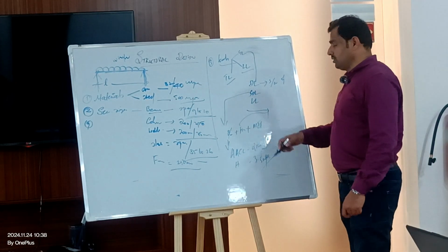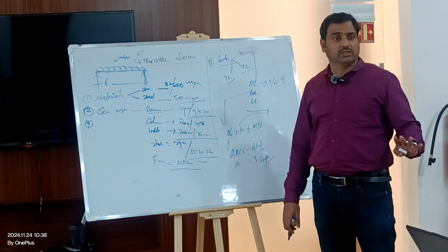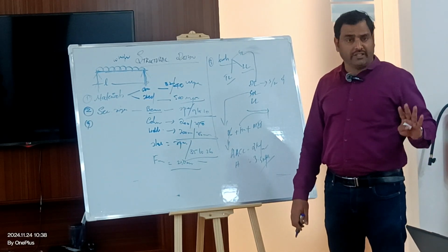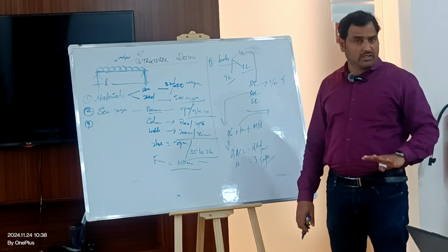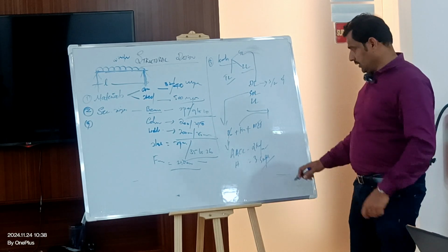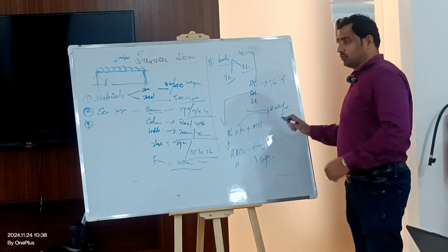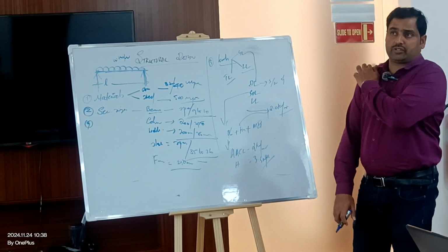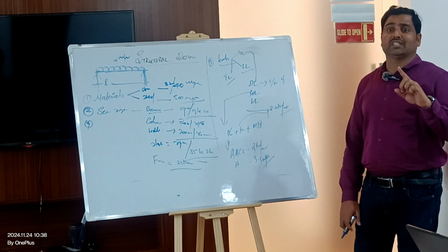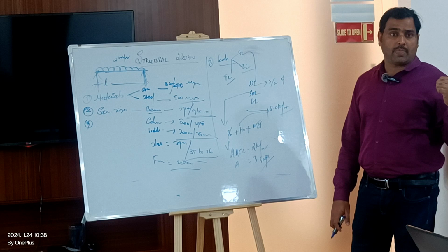How about the finishes? I do have different kinds of finishes. Either it could be tile, marble, or screed, and there won't be any finishes in car parking, correct? There is nothing in car parking, right? I'll make it very clear. As per authority requirements, you need to follow minimum finishes, to be considered as marble, 2 kN per square meter for the marble load.